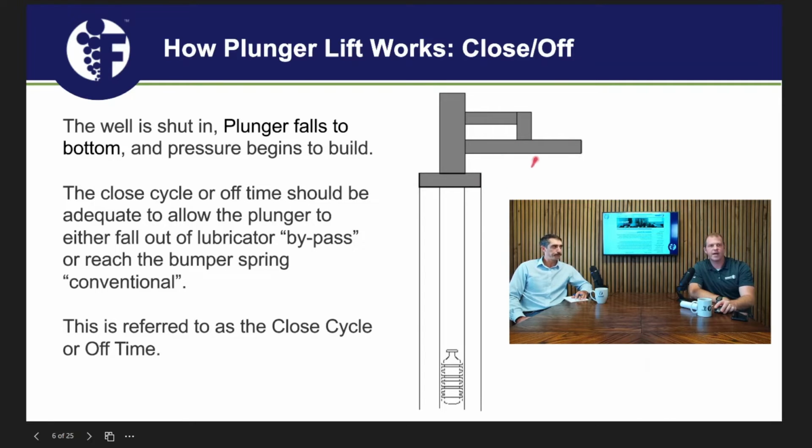Right. Okay. And then when that's being closed, that's either an electronic or a pneumatic valve. Yeah, historically it's been pneumatic, right? But as we see the industry make shifts trying to get rid of emissions and whatnot, a lot of it's going to electronic. Because the pneumatic ones typically vent off from that supply gas.